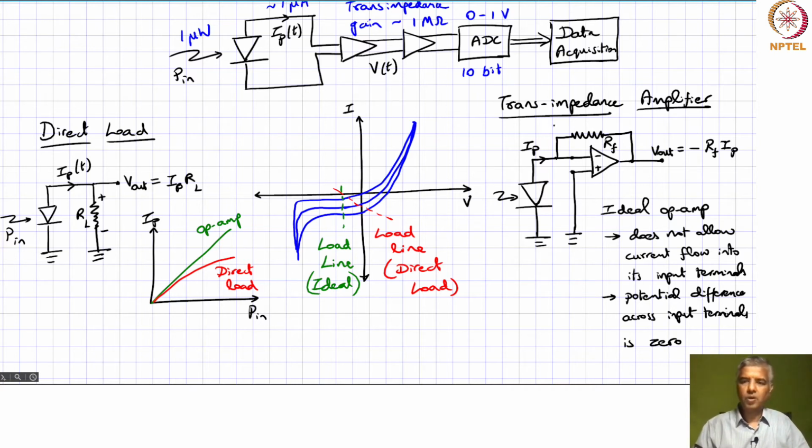You have to also consider certain feedback capacitance here, CF, which could be some spurious, parasitic capacitance that you incur in your board, or this resistor value itself can exhibit certain capacitance. So you have essentially an RC circuit in the feedback.